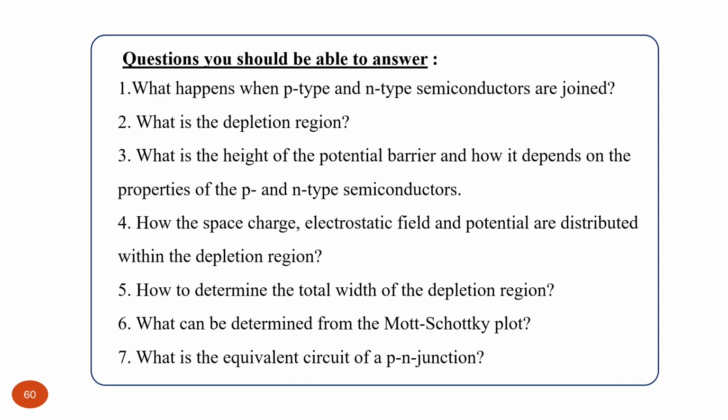We will continue next week with the analytical derivation of equations for the current voltage characteristic, because so far we considered how we form the space charge distribution, electric field, electrostatic potential, band bending, thickness of the depletion layer, capacitance of the depletion layer in terms of its voltage dependence, and also what we can extract from this voltage dependence of capacitance. And also at the end, quite an important moment, we discussed in detail how to correctly measure this depletion capacitance.